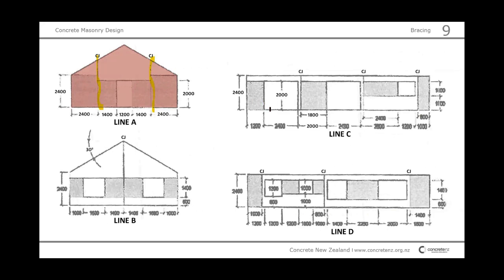So unlike with timber buildings, let's say 3604, timber buildings, we have studs everywhere, and here we have to brace the spaces between the studs, which is not necessary for masonry because the block itself is already braced, nothing happens. This is why we only brace the openings. And so here's just a bracing panel, which would actually provide many more bracing units than if the panel would extend down here. So this panel provides possibly 1.5 times the bracing units the entire panel would give us.